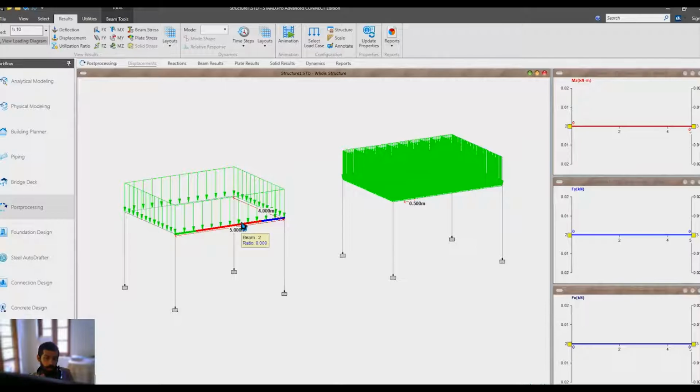Basically, the purpose of a beam is to capture the load from the slab and transfer it to the column. But in the first case, since we didn't provide any meshing, there is nothing on this beam. There is not even a single load, no moment, no shear, and no axial force, which is very sad. Come on guys, this is very sad.